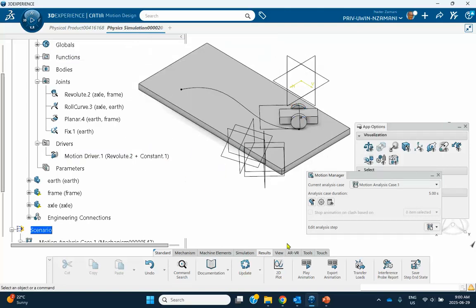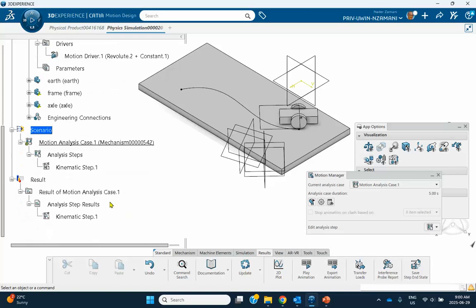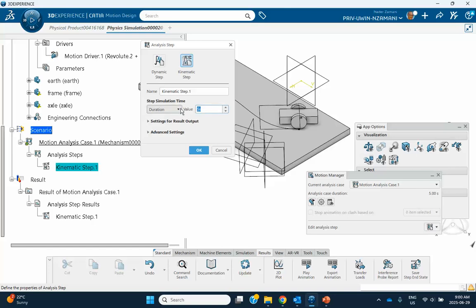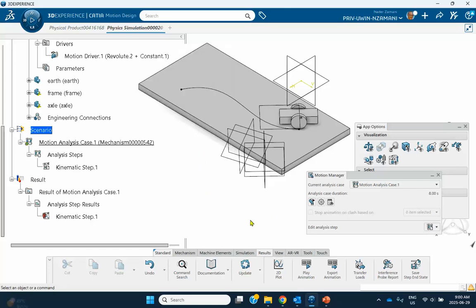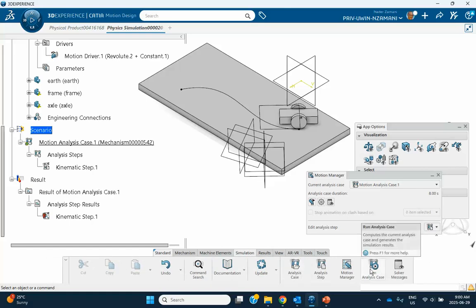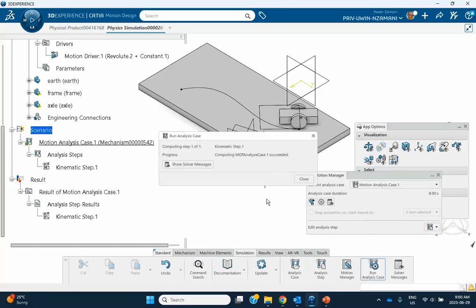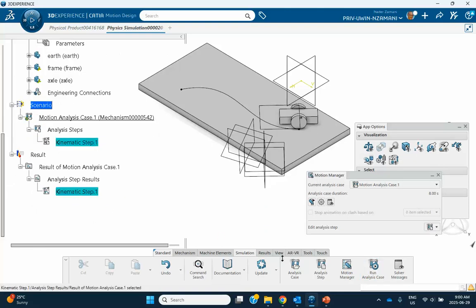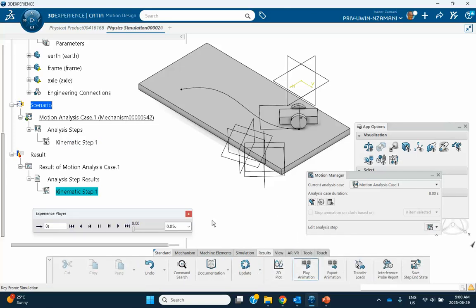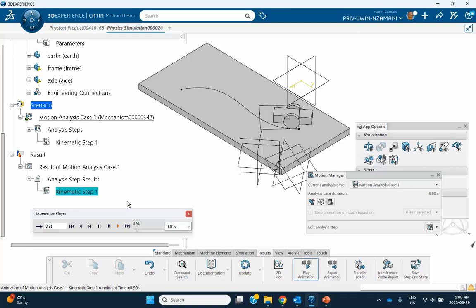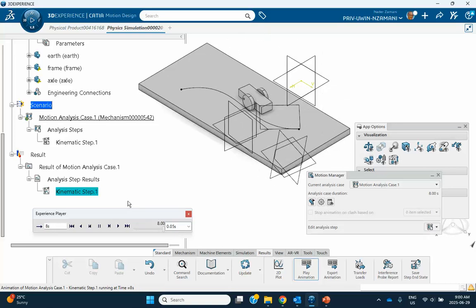Okay, that's good. And we have to run it. By the way, let me change the duration to 10 seconds, maybe 8 seconds longer. Simulation, run, wait until it finishes. It finished, and select the result. Go to results and animation, and play it. There's physics here, okay? Because I put the velocity in there, you can, for example, calculate the velocity of a point and acceleration of the point, etc. It's not just a cartoon.